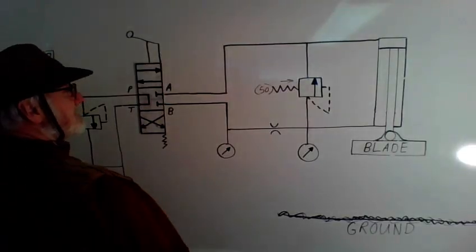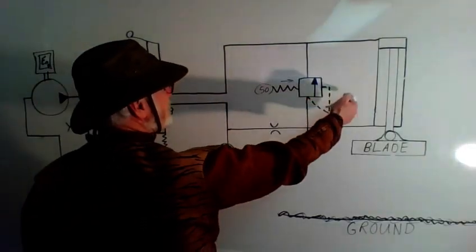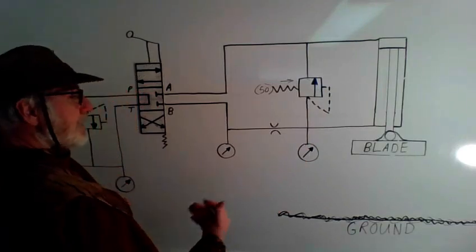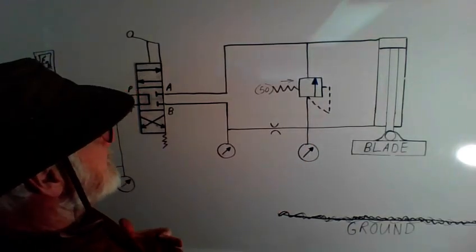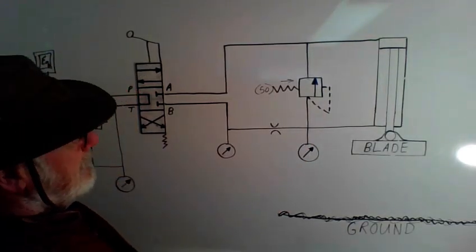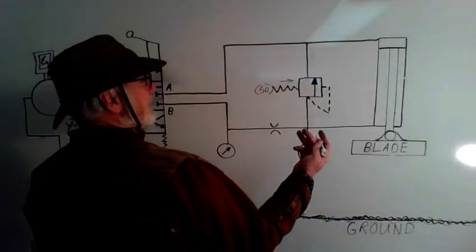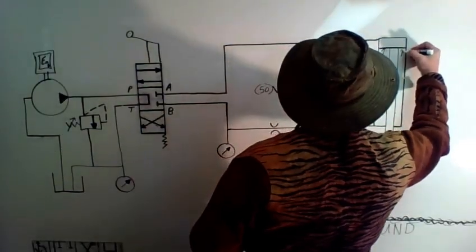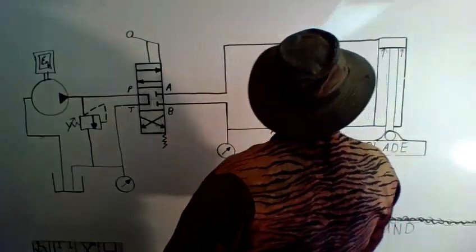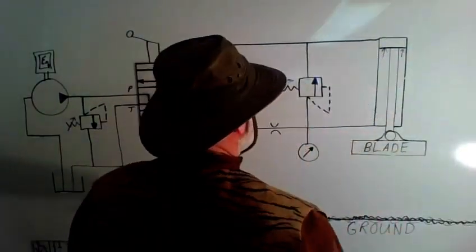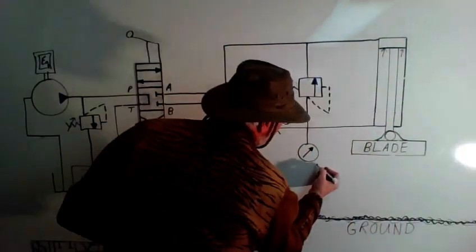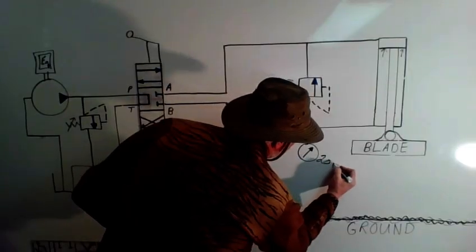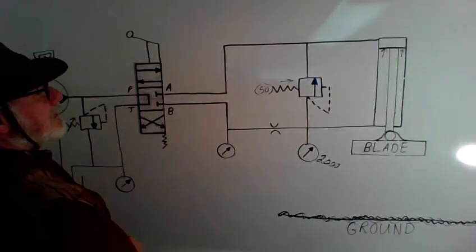First off, there's a few things involved in this quick drop valve. There's a few requirements. One, it definitely senses upstream to open that valve. However, how I've drawn this initially is the blade is up in the air. So if the blade's up in the air, then logically it's going to require some kind of pressure in order to hold that blade up in the air. And let's just give this an example of maybe 2000 psi.